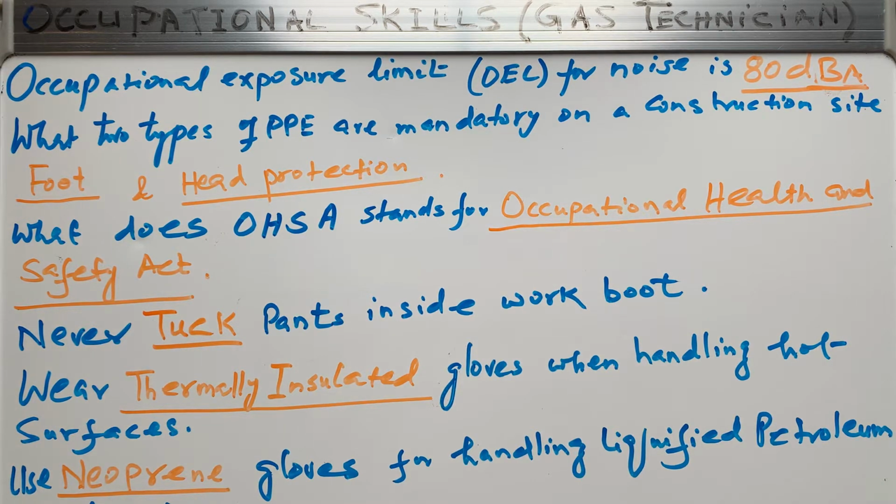Whenever, because noise can affect you, and there are lots of tiny fibers in our ear that help us to hear. And those tiny fibers, if damaged once, cannot be repaired. So we have to protect our ears with some sort of hearing protection. Those commonly used are maybe disposable earplugs or reusable earplugs or earmuffs or those kinds of things, right? So remember that headphones or earbuds for portable listening devices do not provide hearing protection.